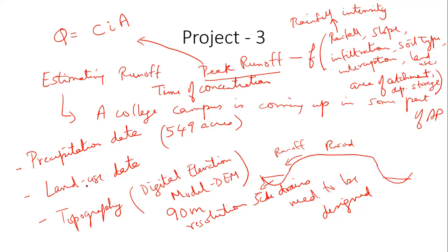So in the case of IIT Tirupati, for example, all the construction that is going to happen on the campus is going to happen within 30% of the overall campus size, right? Out of those 550 acres, you're not going to build everywhere. We will have lots of open spaces. We'll have green cover and so on. So you can assume something similar, right? You can assume that only 30% of it is going to become impervious surfaces. The rest of it will be whatever is currently existing, right?